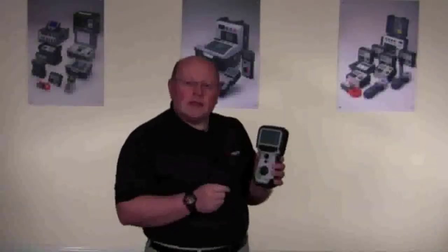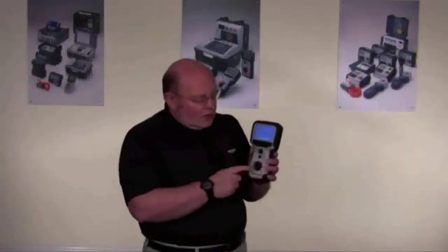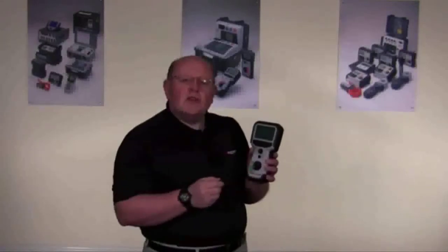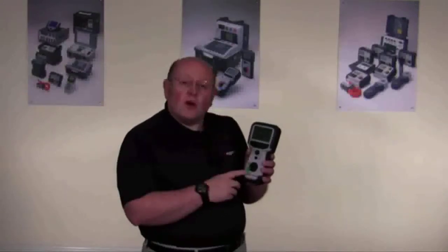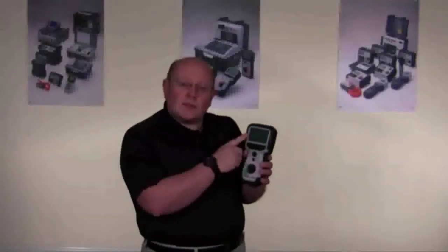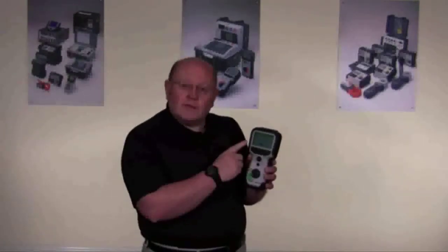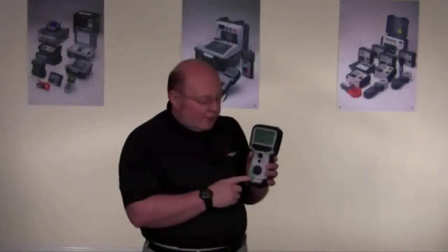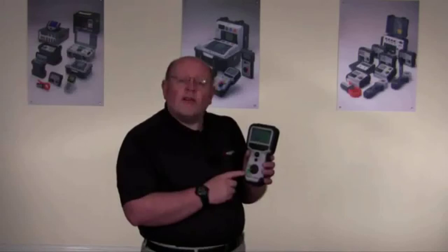The manual settings on the TDR are twofold. They are designated as 2 and 1, and these positions give you the same sort of operation. The difference is that in position 1, you're operating cursor 1 on the display, and in position 2, you're operating cursor 2 on the display. These positions take what you have set yourself in the setup, which we'll go into in a second, rather than the automatic features that the instrument would choose for you.